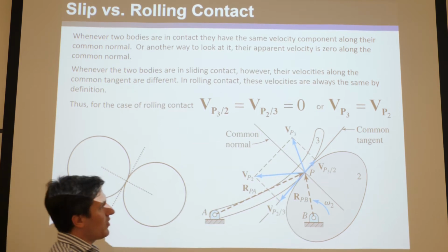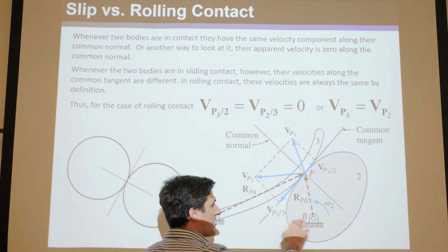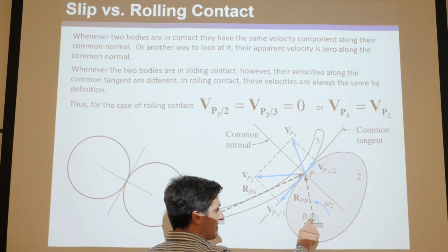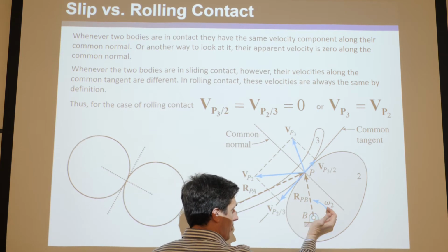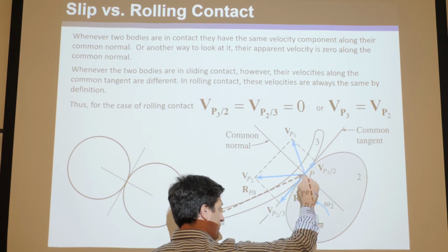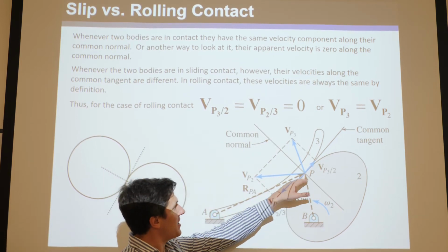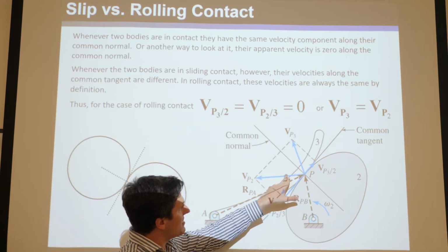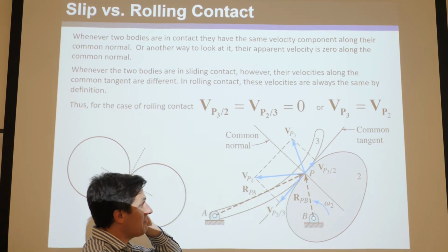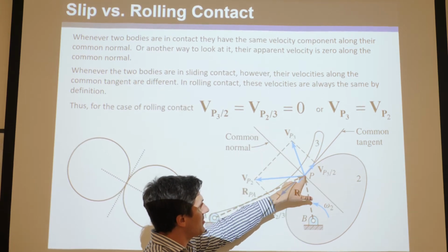And what's the absolute velocity of P2? We could do the velocity difference equation for this as well. What's the velocity of that, VB? Well, 0. Then you add that to omega 2 cross RPB, and that gets this velocity, which is the velocity of P2. And again, these have to be 90-degree angles. So you can see, here are the two: that's the velocity of P3 and that's the velocity of P2 at that instant.